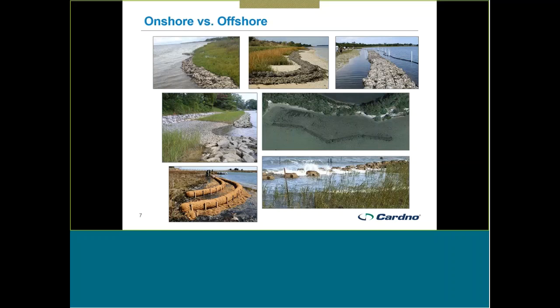So you've got, in the upper left, these projects that are right at the edge of an existing shoreline. This looks like oyster shell bags put right at the edge of an eroding marsh, kind of a marsh toe revetment using shell material. Similar design, but it's moving offshore, either moving offshore a little bit or the shorelines continue to erode. And then you can just see this progression. These are, I'm going to guess, reef balls or oyster castles just offshore, so they're providing an energy attenuation function. A toe sill, and we'll talk in a little bit more detail about some of these techniques.